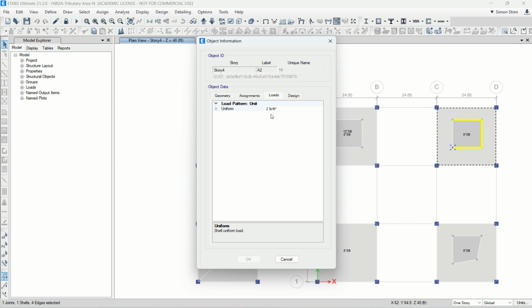But before, if we didn't have this feature, this is more of an ETABS thing, other software might be different, I had to draw more areas manually, select the area elements and assign the proper loading manually.